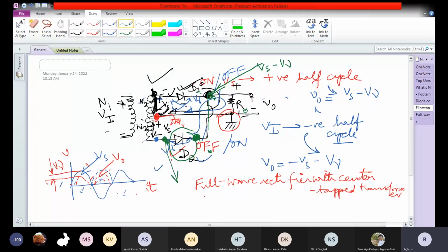What is the voltage here? The voltage here, because it is going through the reverse bias, is minus Vs. Because the voltage here is 0. It is grounded. The voltage at this point is ground. So the voltage at this point will be minus Vs. It is below 0. So this drop is Vs. Therefore, the voltage on the P side of D2 will be minus Vs.